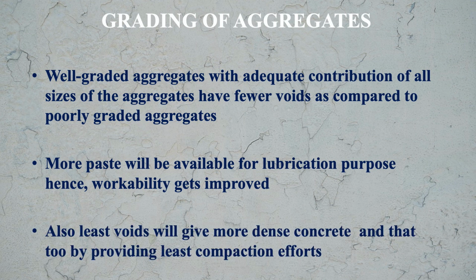Also, because of fewer voids, what will happen? It will give more dense concrete, and that too by providing least compaction effort. Means you have to give less compaction effort, and even at this less compaction effort we will get more dense concrete, and more dense concrete means good strength of the concrete.